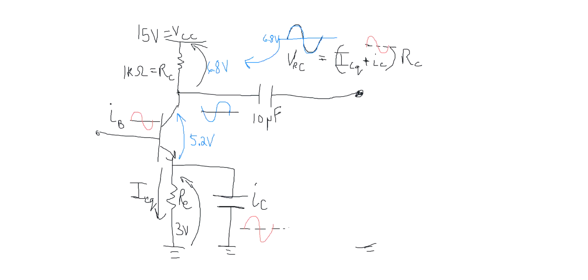That means I'm left with, we said 0 voltage, but I have to say that I'm going to have the minimum saturation voltage at the collector emitter. That would be 0.2 volts. So I have basically dropped 5 volts across the collector and emitter. I'm going to rise 5 volts at the collector resistor then.